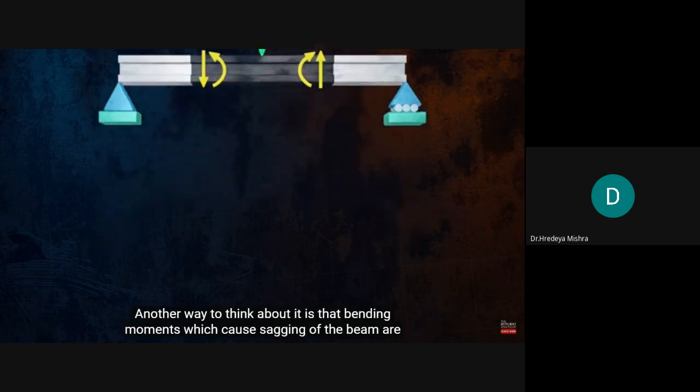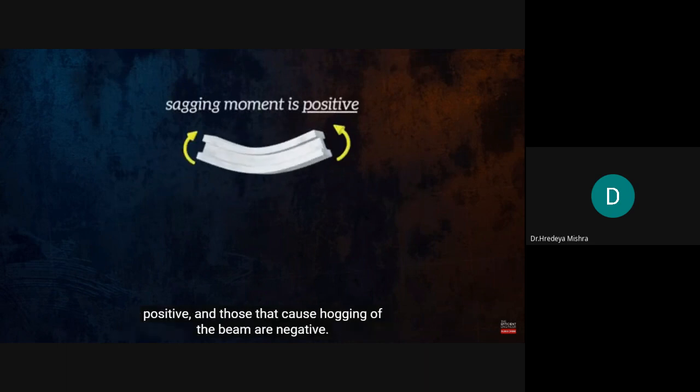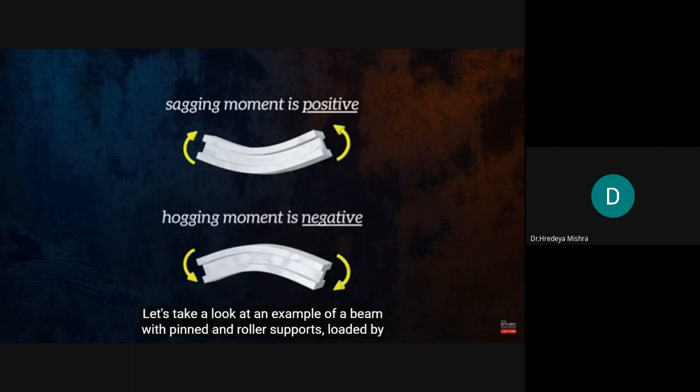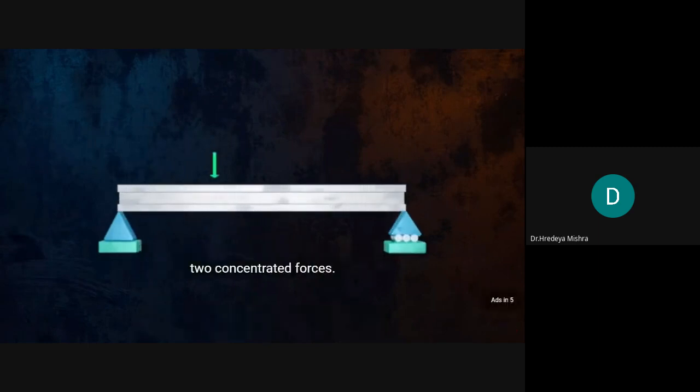Another way to think about it is that bending moments which cause sagging of the beam are positive, and those that cause hogging of the beam are negative. Let's take a look at an example of a beam with pinned and roller supports, loaded by two concentrated forces.